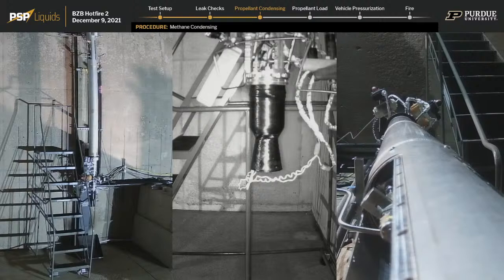Next question in chat. Yes, we do model the changing thrust from changing throat area for our sims. And we also model changing thrust based on tank pressure. And we integrate this directly into our simulations so that we get an accurate altitude prediction for the flight.